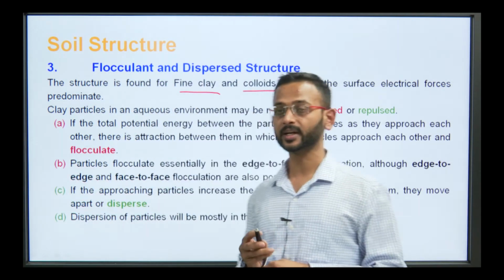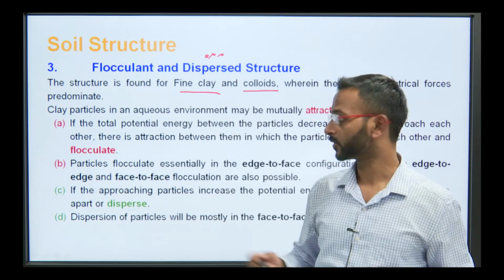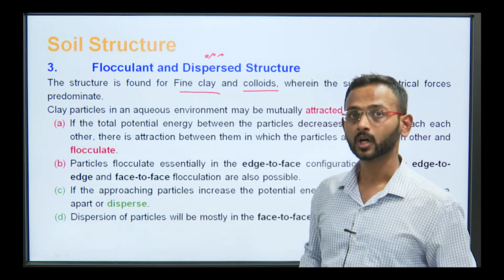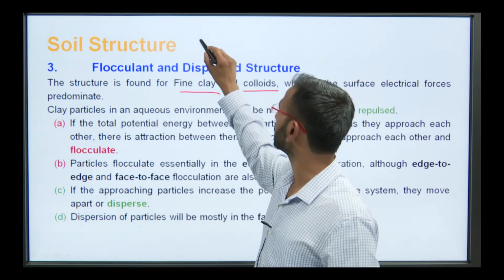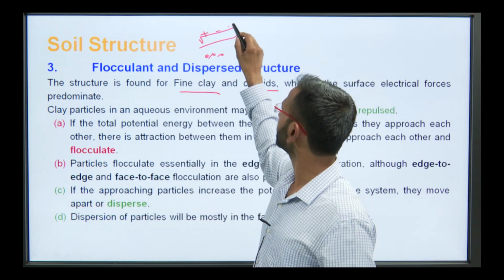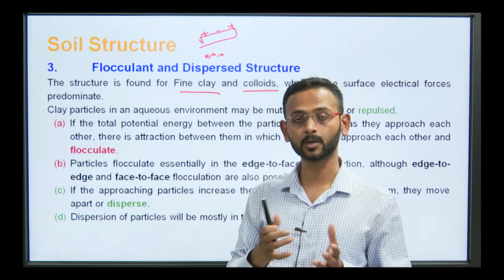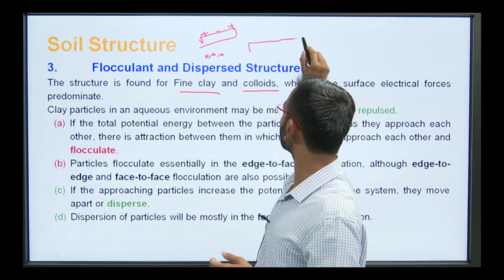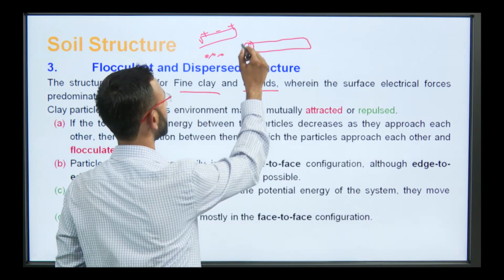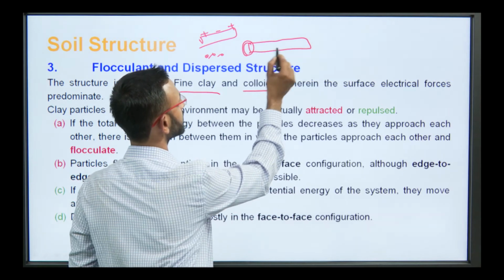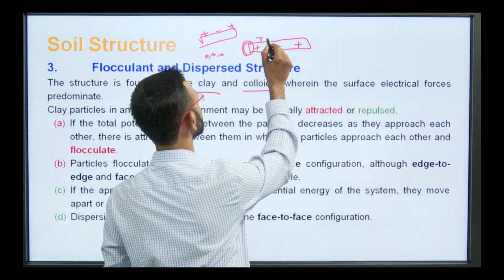So, clay particles in an aqueous medium. These are very fine particles, very small particles. The clay particles in an aqueous medium may be mutually attracted or repulsed due to the surface electrical forces. Let us say there are some plus and minus charges. We also know that fine particles have a flaky nature. Flaky nature means one dimension is very small, so it has this type of dimension and it may carry this sort of charges on the surfaces.